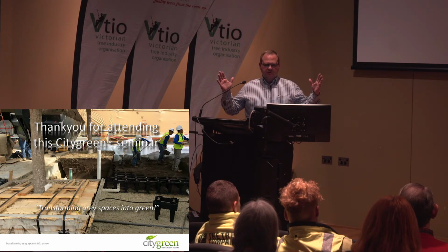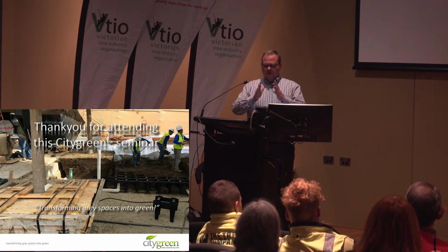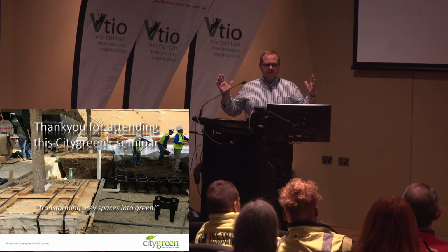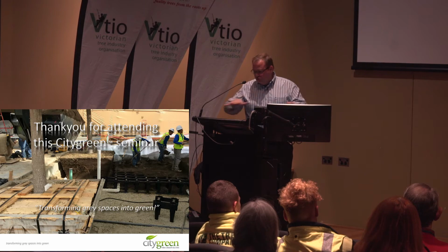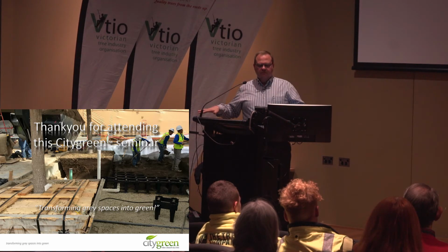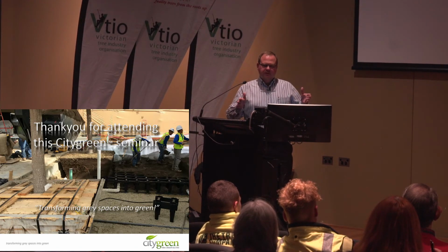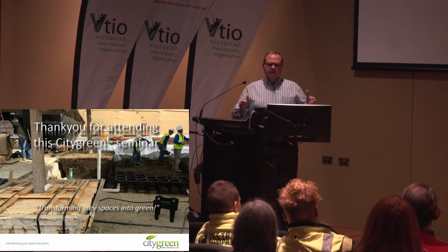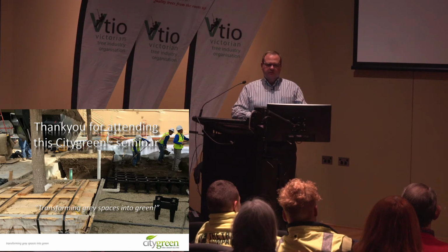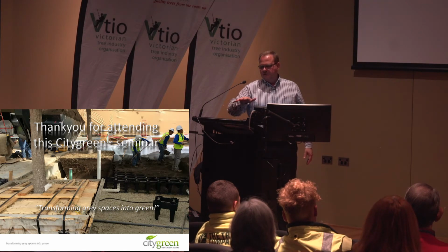In our standard recommended designs, a lot of the projects we see now, the tree root ball actually sits in an opening, and then the roots grow into the soil that's within the structure. Now, if that tree fails or reaches the end of its life, the recommendation is just do exactly what you do with any tree. Remove the canopy, cut the roots if you can, but grind the stump out, create space to plant another tree, put some more soil in there, and the roots of the new tree will use the decaying roots of the old tree basically as a corridor. That's how it works.